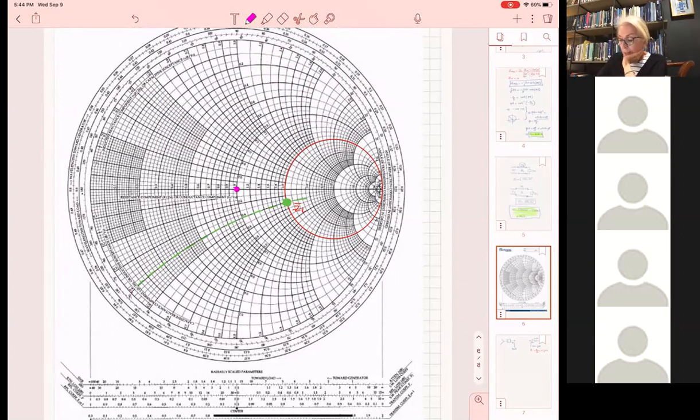And usually on a Smith chart, what we did there, we changed the real part first, all right, before in the approach. But on a Smith chart, they always tell you the following. If you are to move from one point to the center, you can either move on circles that are centered at the center of the Smith chart, and they are the equal VSWR circles.